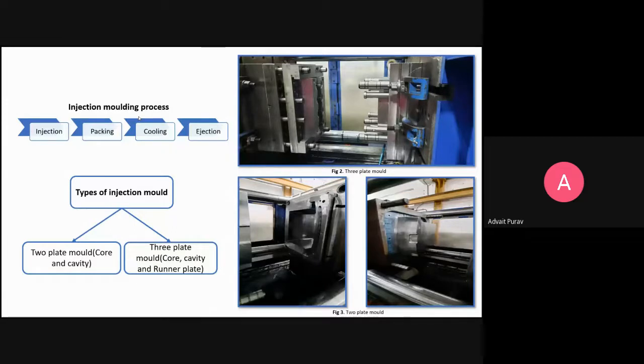So the cooling channels are actually straight drilled, okay? They are straight drilled through and through that particular mold. For example, this is a particular mold, so if you can see these holes over here, these holes are actually the cooling channels. The tubes and so on are not fitted yet, but the water is circulated in and out through that particular mold or that plate.